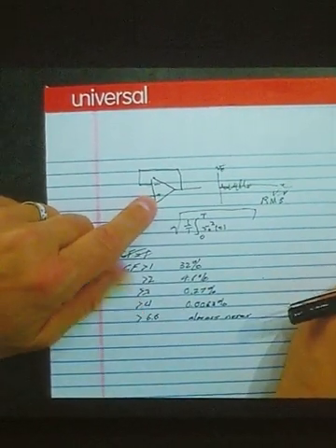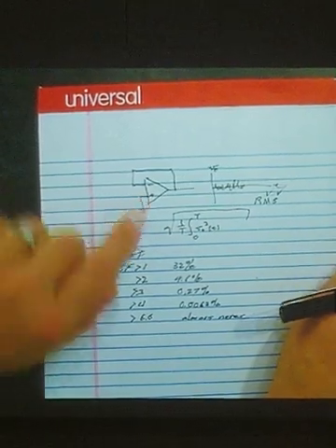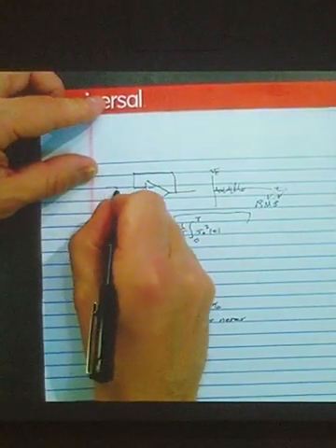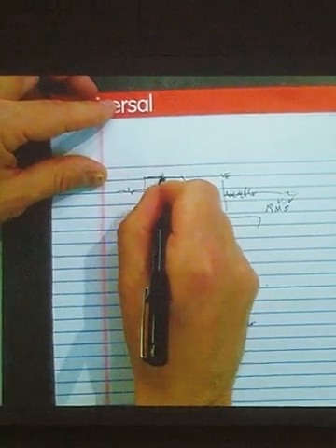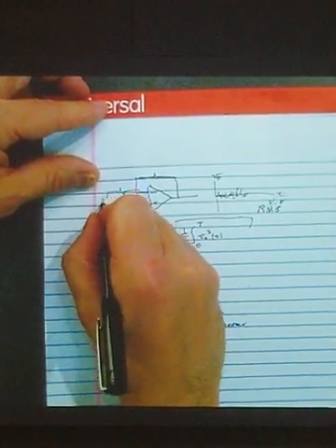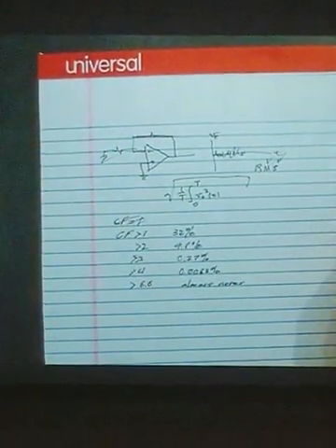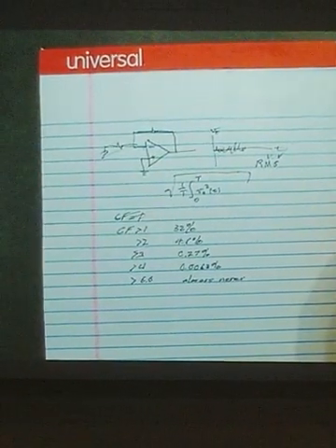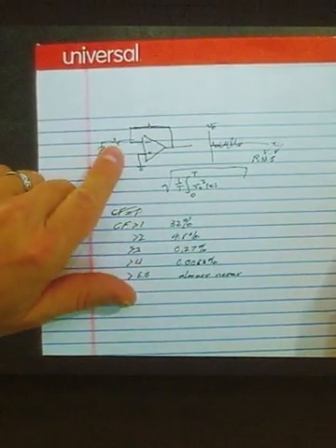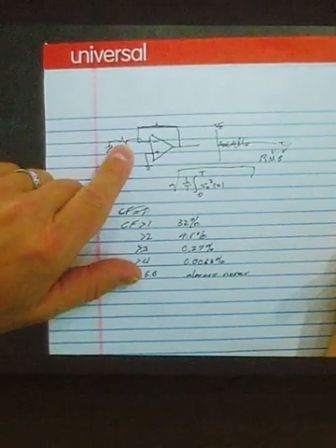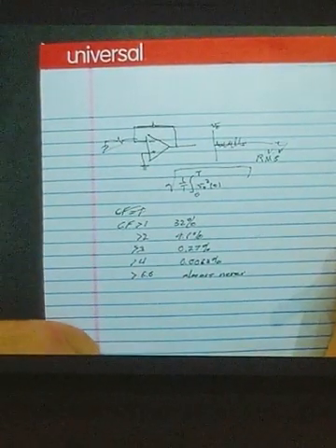If we set this up with a gain of 100, as a non-inverting amplifier, like that, with a resistor here, it's reasonable to ask, do the resistors add noise? Yeah, they do, but we can show that it won't be that much.